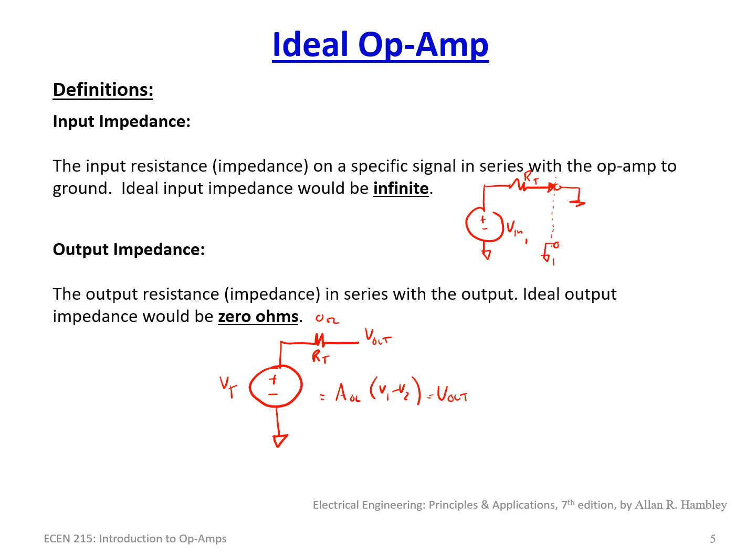If there is a load resistor RL here that is something other than infinity, it's going to pull a current and affect the voltage here. V1 is not going to be the voltage at this point, VN, which is what we really want. We want V1 equal to VN, which requires RL to be infinity ohms. That's why we want the input impedance to be infinite.